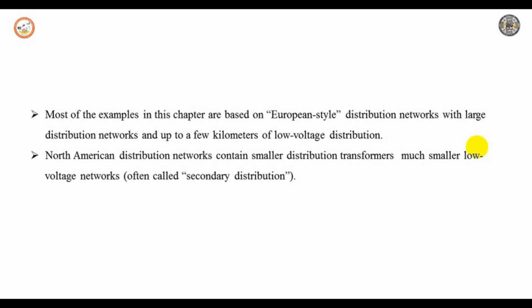According to IEC 61000, various types of voltage fluctuations are defined. Among those, type D voltage fluctuations are characterized as a series of random or continuous voltage fluctuations. A load that can exhibit continuous or rapid variation in the load current magnitude can cause voltage variations. So they are referred to as flickers.